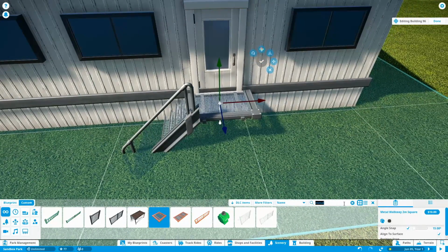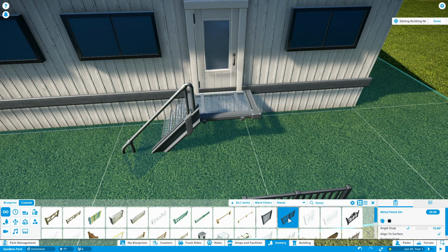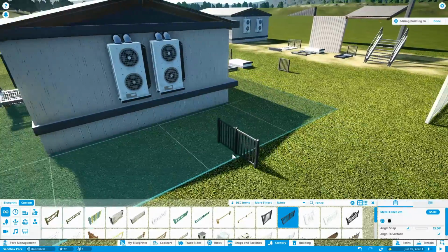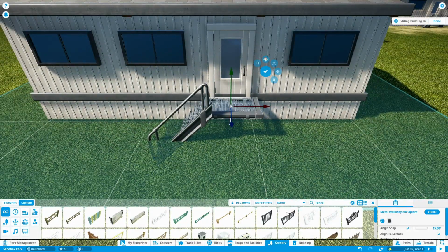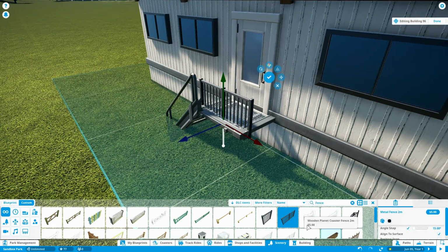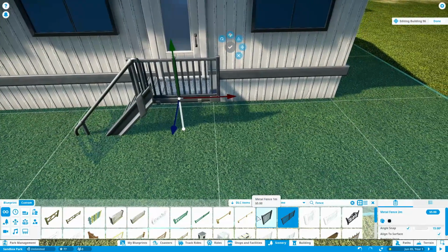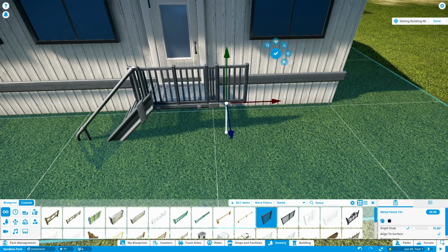And then we're going to search for fence. So you got this 2-meter fence from over here. And same thing, we're going to go off of there. So select it, hit Control X, and then select the new piece you want. Raise it up a little bit. Now I want this piece, so again, we're selecting that instead.